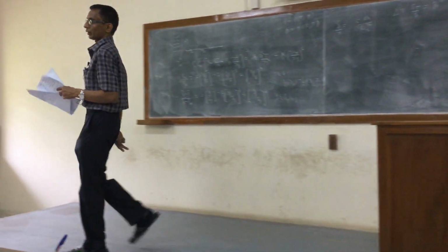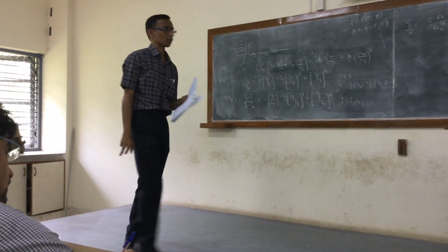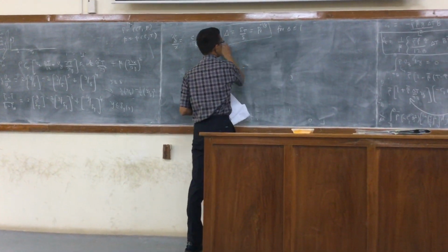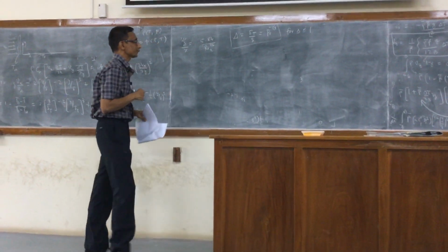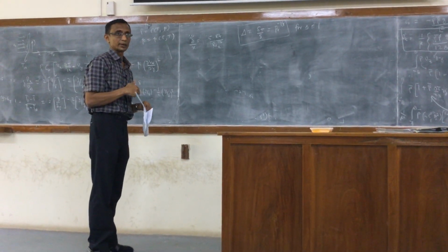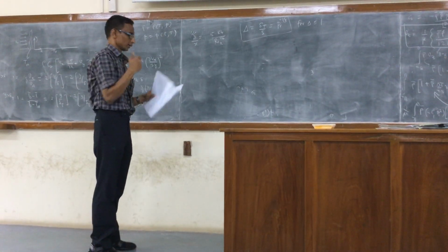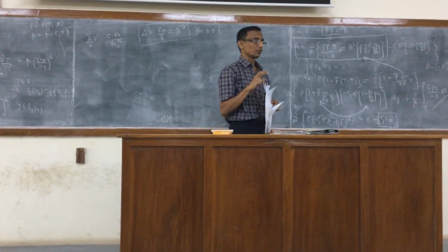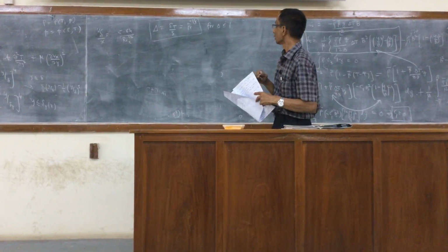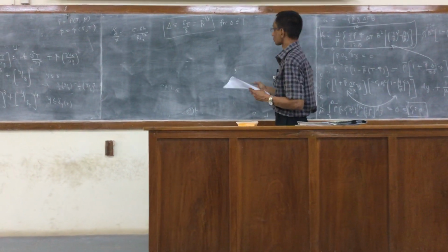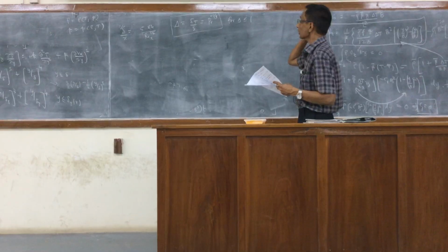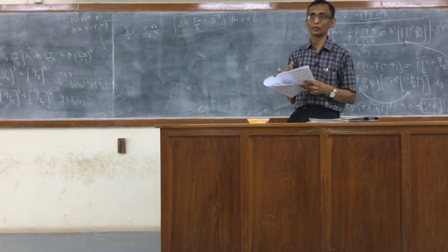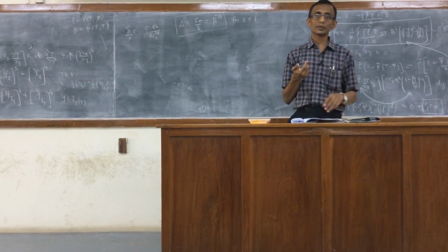What greater than 1, I haven't seen the expression in words yet. So obviously this is certainly valid for when the thermal boundary layer thickness is less than or equal to the hydrodynamic boundary layer. So you can easily infer roughly what will happen for various values of the Prandtl number. If it is a gas, the Prandtl number will be of the order of 1, right?